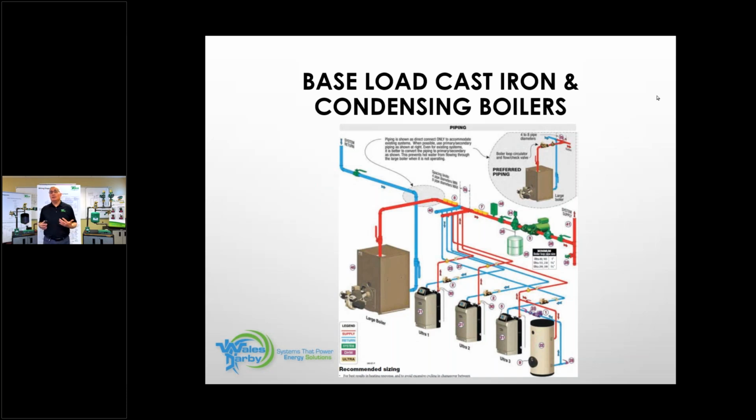Well, you can still do this because what we're showing you here is really no different than what you would do residentially. Yes, the last boiler, the way it is piped, has now become a radiator. But you know what? It'll work fine on this job. You know what'll happen? After a season or two, after they see how much money they've saved, they're probably going to come back to you and say, hey, let's change that last one out, turn that into a condensing boiler, and then you can really finish it up and make it a nice primary secondary system.